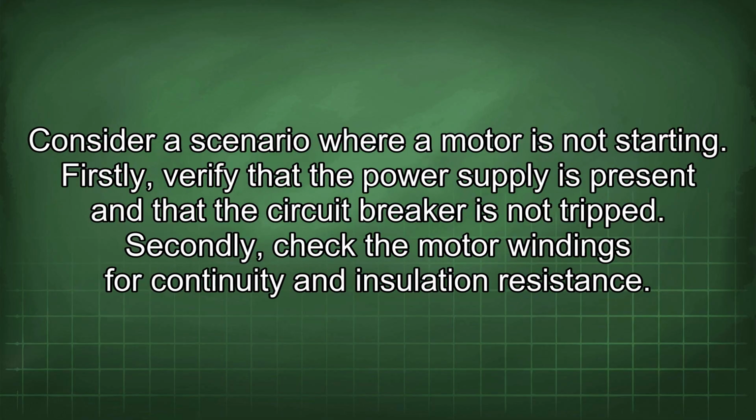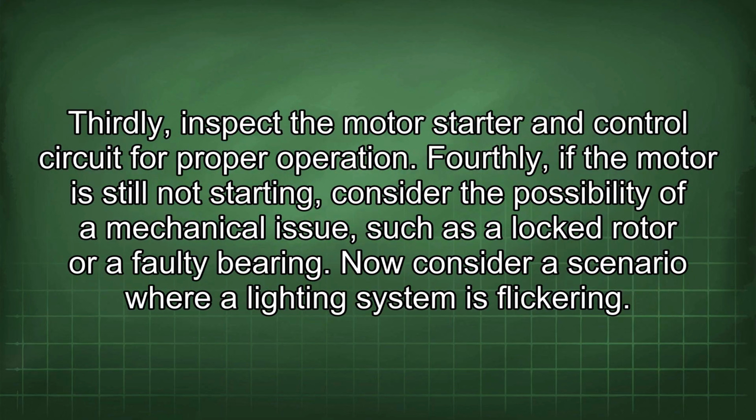Consider a scenario where a motor is not starting. Firstly, verify that the power supply is present and that the circuit breaker is not tripped. Secondly, check the motor windings for continuity and insulation resistance. Thirdly, inspect the motor starter and control circuit for proper operation. Fourthly, if the motor is still not starting, consider the possibility of a mechanical issue such as a locked rotor or a faulty bearing.